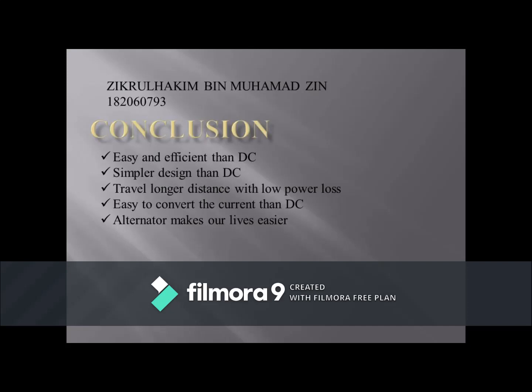Thus, the AC generator is simpler in design than DC. Other than that, the AC generator can also travel longer distances with low power loss than DC. AC has the advantage of traveling over long distances with less loss of power than DC, as transforming the current to a high voltage reduces the current, which in turn reduces power loss. This can be seen from the formula P equals I squared R, where P is power loss due to resistance, R is resistance, and I is current.